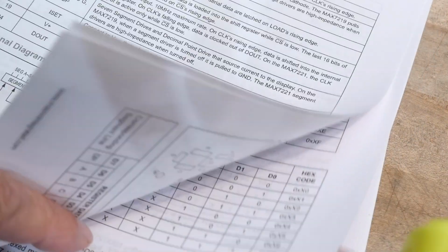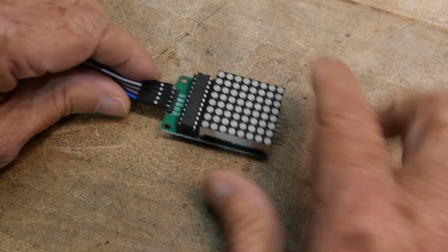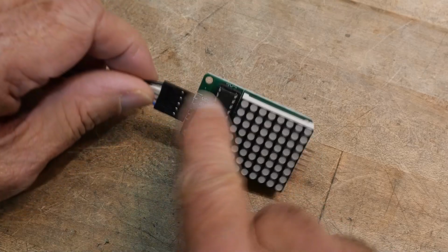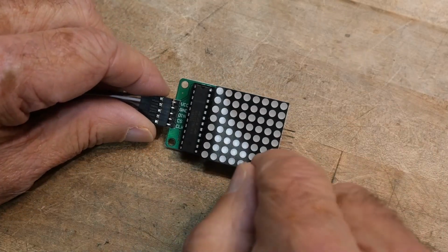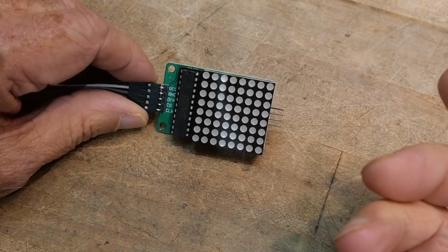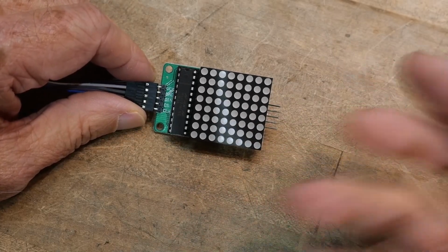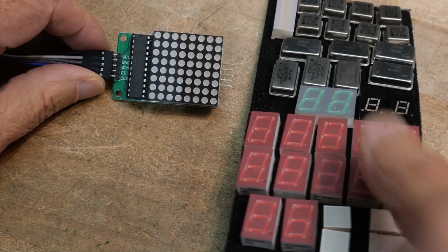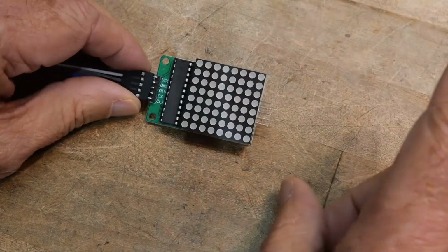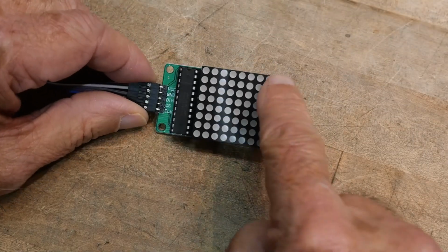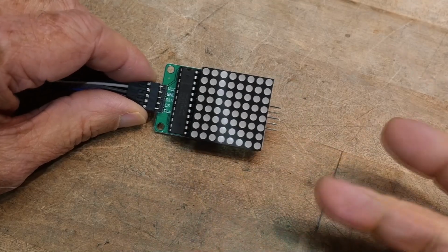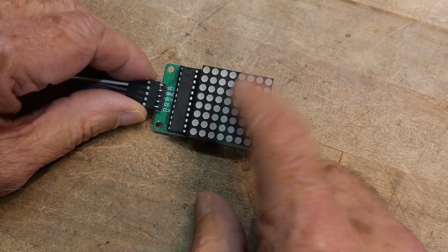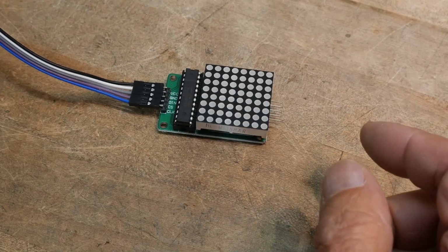All right, and here's the data sheet, it shows you all the things you need to know. But what you want to see is one going. So let's get one going. All right, so here's the chip. It's a big chip. And you said, but wait, it's an 8-digit, 7-segment display, like all these guys. Nope. We're going to use it a different way. We're going to use it as 8 digits, 8 segments, using the 8 and 8. And you can do that also with this part, which is what I want to do with it.